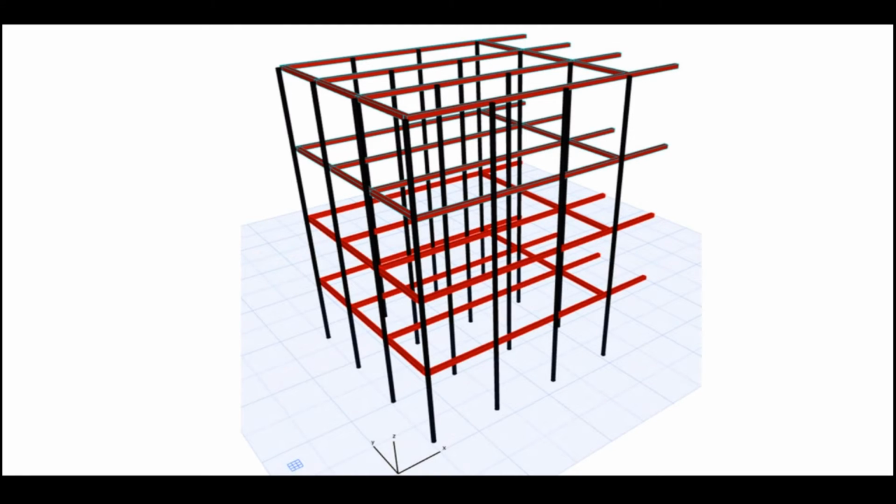So totally, for an 8 cross 8 cross 8 LED cube, we will have 8 into 8 columns and 8 layers, right? So now, if you have to get this LED to glow, what you will have to do is give a signal to this and give a signal to this.